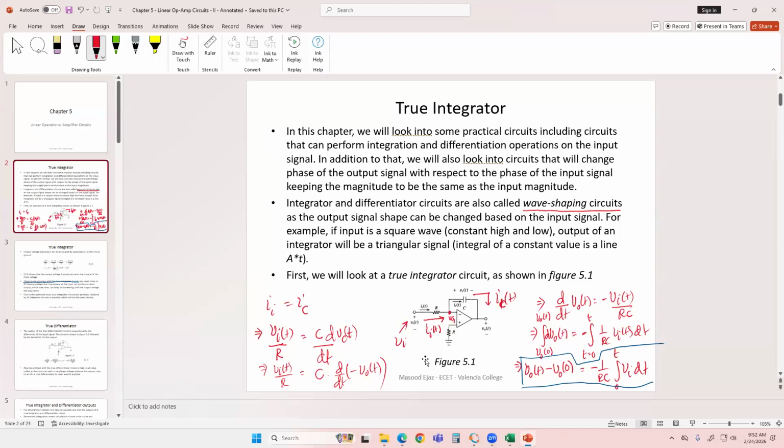No matter how small that quantity is, since that's a DC value, it may be in microvolt, it may be in nanovolt or whatever. But if you just leave that circuit on, what's going to happen? Over time, it's going to start increasing and start becoming a ramp, because your input is a stray noise voltage or the leakage current from the biasing sources or whatnot.